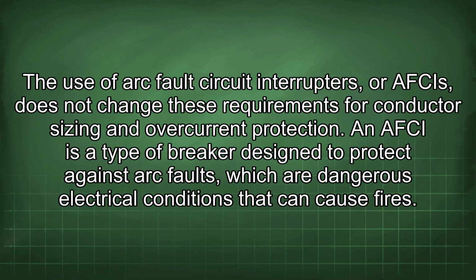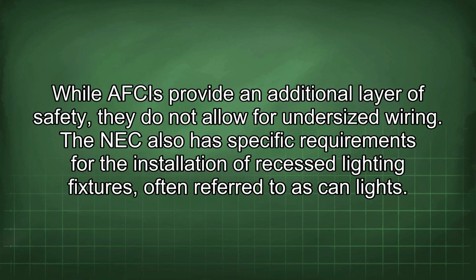The use of arc fault circuit interrupters, or AFCIs, does not change these requirements for conductor sizing and overcurrent protection. An AFCI is a type of breaker designed to protect against arc faults, which are dangerous electrical conditions that can cause fires. While AFCIs provide an additional layer of safety, they do not allow for undersized wiring.